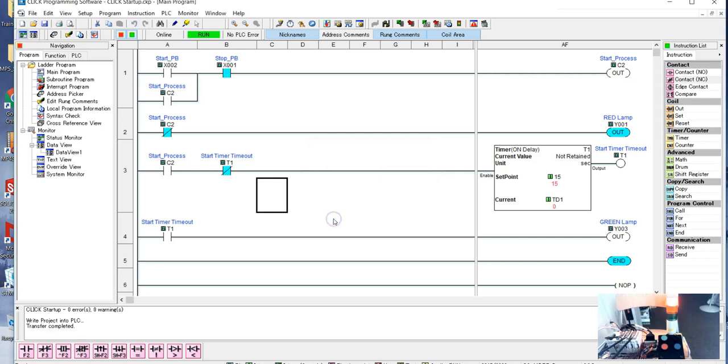And then we'll show you why we would use this in a circuit. Because when we want to make lights blink, or we want to do other functions, we use this in tandem with a second timer. They work together, one timer turns on the other timer. So again, it counts up to 15, but then it just goes right back to 0, and it just keeps recycling. On the face of it, you're like, well, that's not that grand of a scheme.